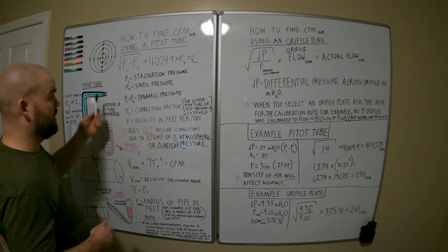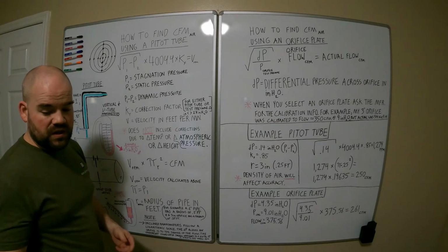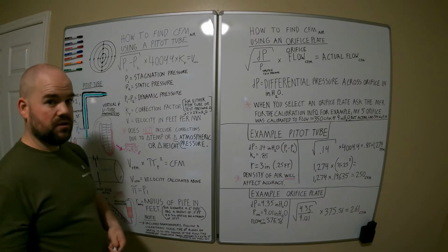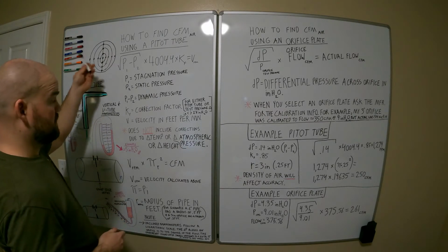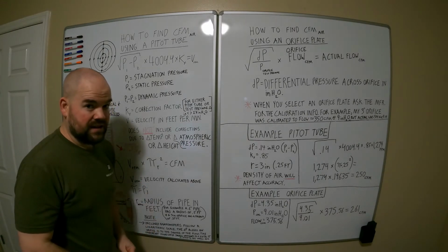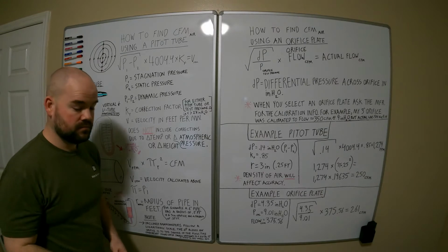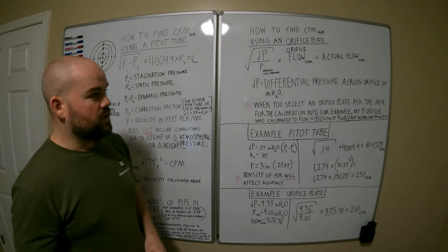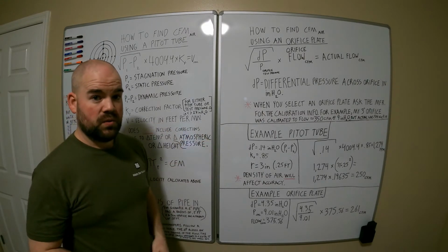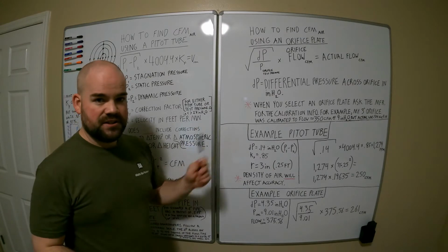And I have literally got within 5 CFM accuracy out of this. So it's a cheap process. You can get a pitot tube for 100, 150 bucks, get the Testo 510 for 100 bucks. And you're going to get really consistent results if you do it several times and average them together. Now, some people don't want to have to do that, which I changed my mind and I switched mine to an orifice style. And my next video is literally going to be me going over a flow test on my new bench. But before I got there, I wanted you to understand why I switched from this to this and how you use both and why what I'm teaching you has validity, that I understand what's going on here.